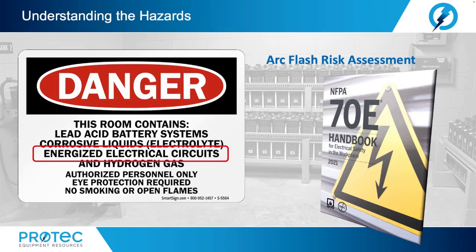In these documents, for instance, 70E, Table 130.5C can be used for establishing the likelihood of occurrence of an arc flash incident based on the task that we will be performing. In the Canadian document, the Z462, we would find this in Table 2.